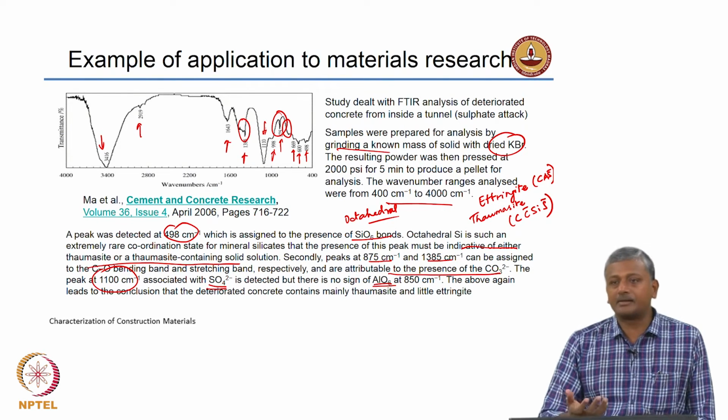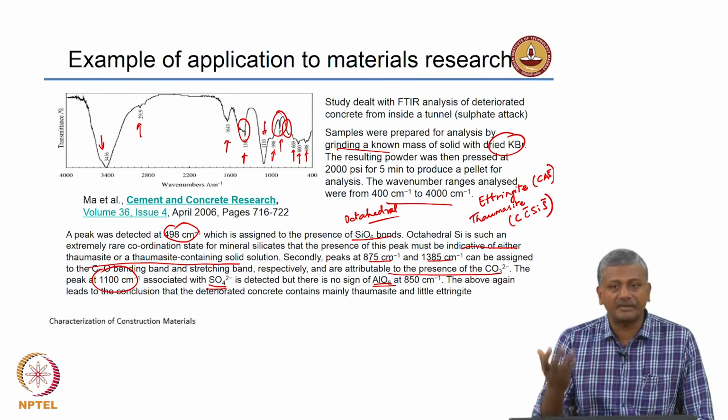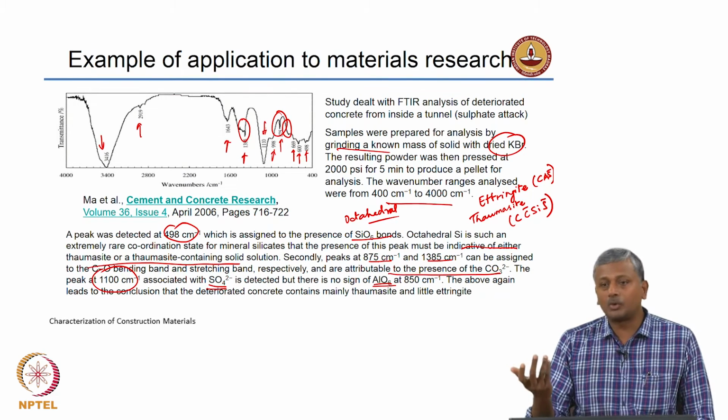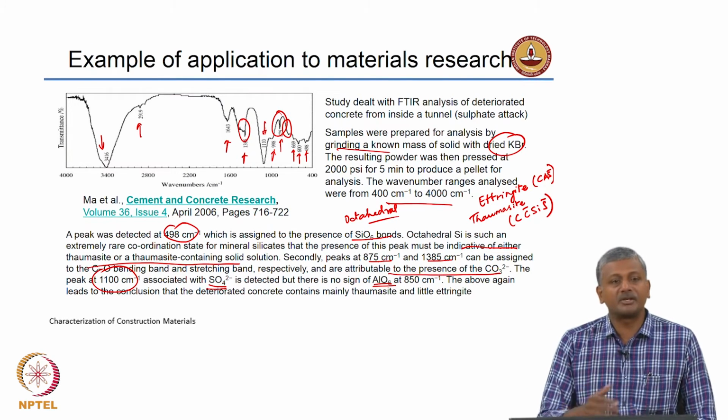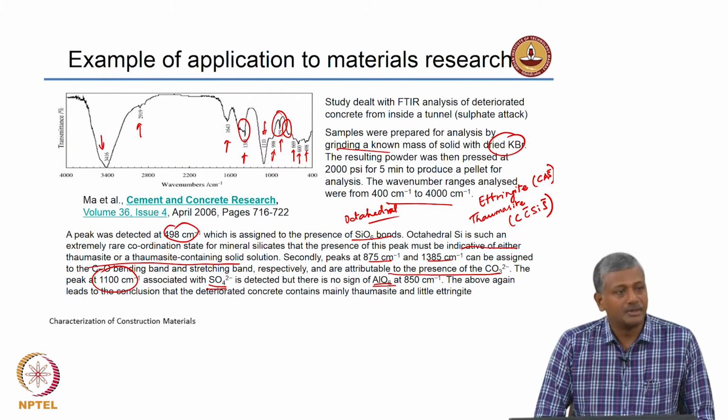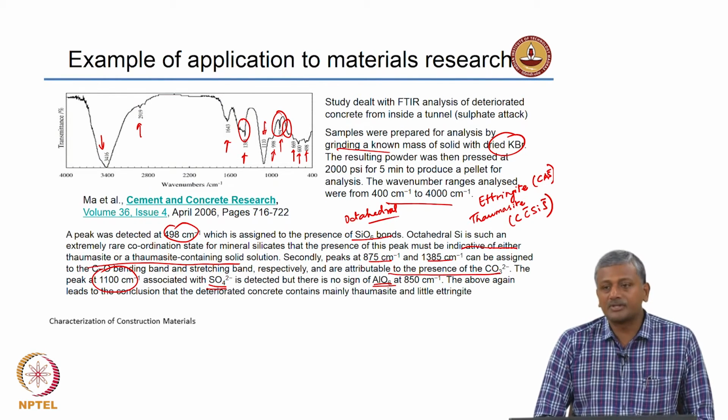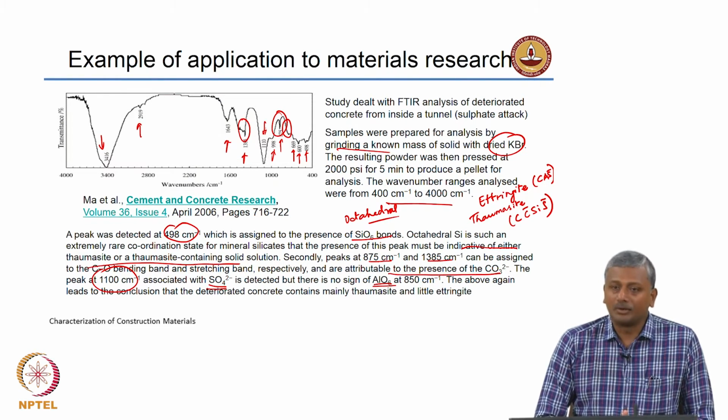Whereas for backscatter electron imaging the specimen preparation itself takes nearly 24 hours, including epoxy impregnation and then polishing to different levels, coating, all those kinds of things need to be done. So, that is not easy at all.